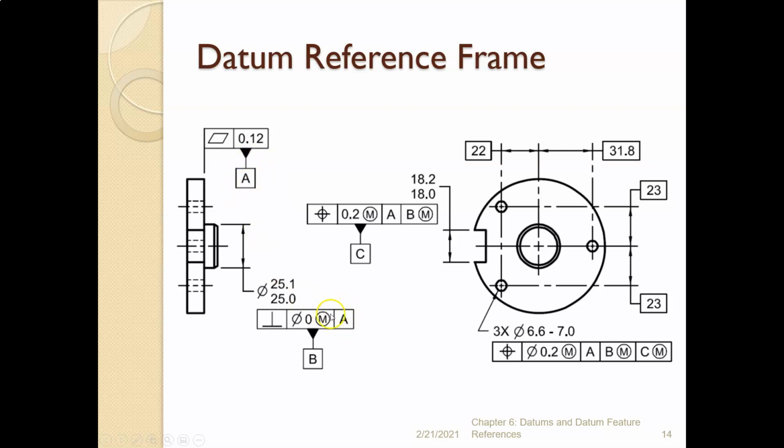And we can see that here, here, and here. Now, we also want the secondary datum to be this cylinder, because that's also important. We want the cylinder to go into the hole straight. And so that becomes our secondary datum. And that's what we call out here.